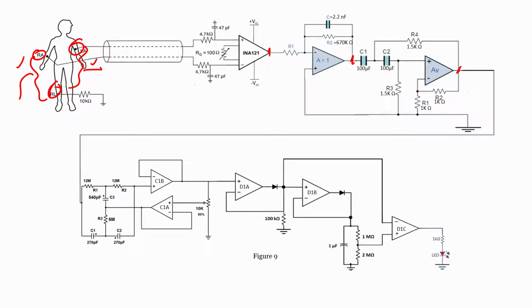But a differential amplifier cannot be used in this application, because the output that we get from the subject will be all common mode signal, and we require a higher CMRR value. A differential amplifier will always suffer from CMRR, and the input impedance of our instrumentation amplifier is higher compared to the differential amplifier.